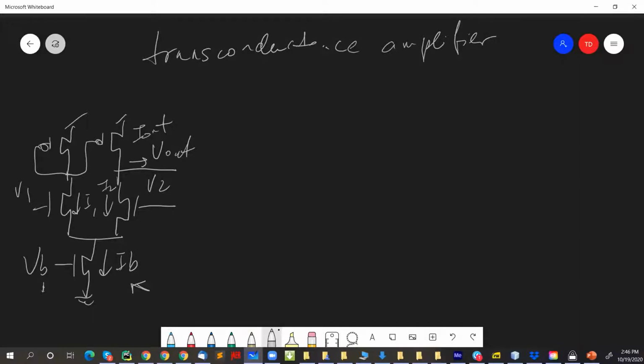Can we assume that the current goes out on the out, and it doesn't have to necessarily flow from the PFET above to the M2? It depends on what you hang on V out. It's very possible for current to flow out of this circuit. If you're operating open loop, you don't hang anything on V out, you just measure V out. Depending on V1 and V2 changing, the I out that you get in the end is going to change V out so that everything satisfies Kirchhoff's current law in steady state. Okay, perfect, thanks.